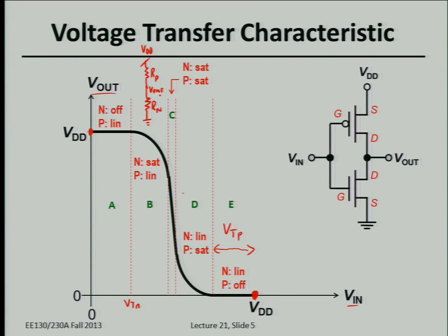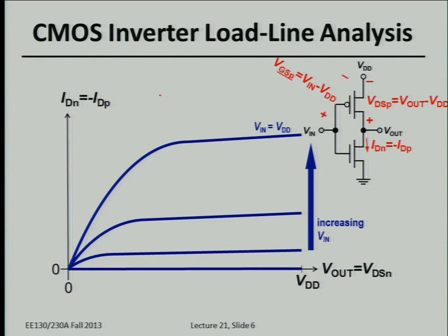And again, you have a voltage divider effect. But similarly, the PMOS device, when it's starting to turn on as you lower the input voltage, is operating in the saturation regime, and it's going to have higher effective resistance than the NMOS device. So the voltage is going to be closer to ground than to VDD. Okay, so basically we're going to go through an analysis. This might be a little confusing, but there's a point to this. So this is going to take a few slides.